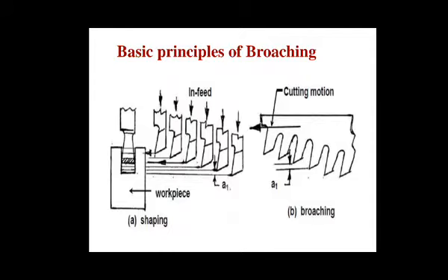The amount of tooth rise between the successive teeth of the broach is equal to the feed given in shaping. Okay, so here you can see in shaping we give so many cuts, but in broaching you are supposed to do just one stroke and you will get the required depth.